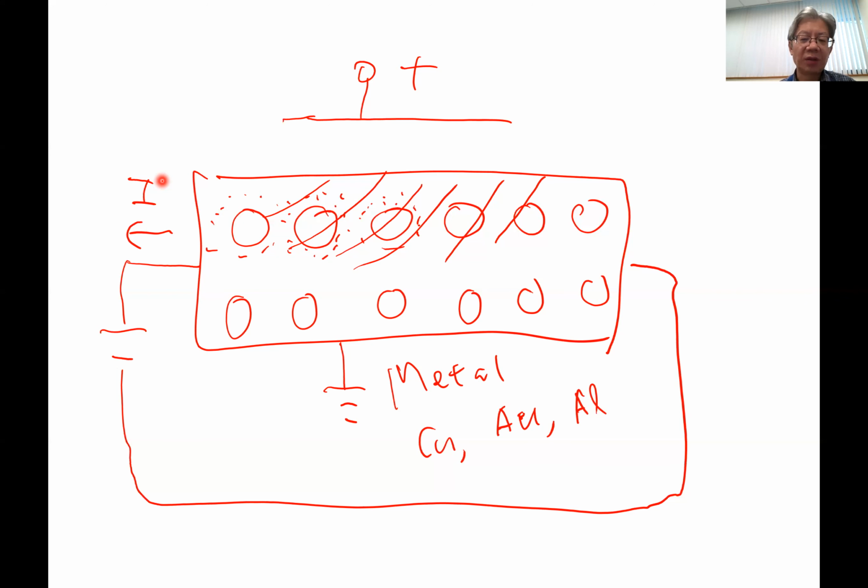Of course, you know that this does not work. What happens is that inside the metal, you have too many electrons. When you apply this kind of bias, it will cause some movement of electrons, for example near the surface. But once electrons move in this surface, because you have a huge number of electrons per unit volume, you immediately establish a backward electric field, which will counterbalance the external electric field applied through this bias. That internal electric field can be very, very strong, because of screening.